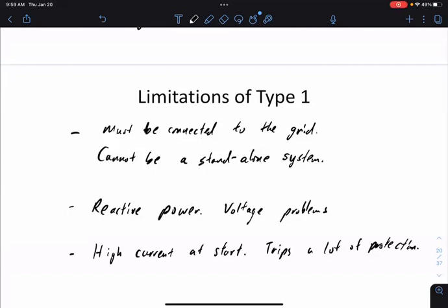And we're starting to see this again in today's grid. For example, we have a lot of renewables, and a lot of them tend to have current surges when you first come on. Protections are not having a good time with current surges. So we solved them for wind turbines, but there are other devices that have these kinds of challenges.